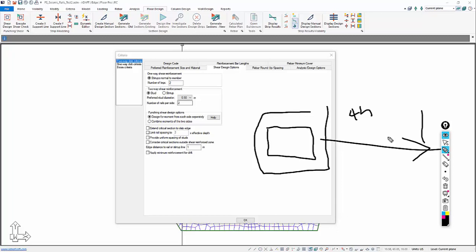It's off or on. There is some wording in the code that if your inter-story drift exceeds a value, then you should check this. We essentially ignore that and just allow the user to turn this off or on. So the user would be required to check that drift, and whether or not, if there's enough sidesway and rotation at a joint, you may need to apply this. That's done outside of the program. You can apply this and the program will reinforce for it.